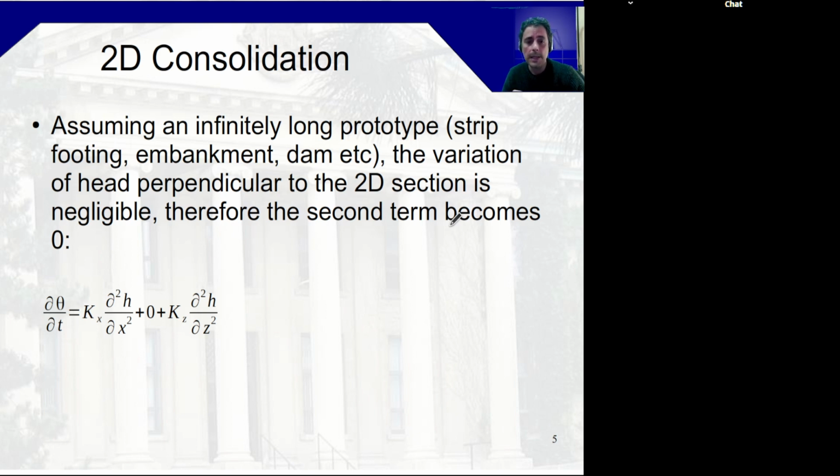So you have plane strain and plane stress. Plane stress means that, in plane strain, the strain only occurs in 2D, so you're confining with enough stress on the other side, perpendicular to the page, that no strain can occur there. Or you can have plane stress, where there's no confinement, so effectively no stress going in the perpendicular direction. So it's important to define what type of problem you have and why it applies.